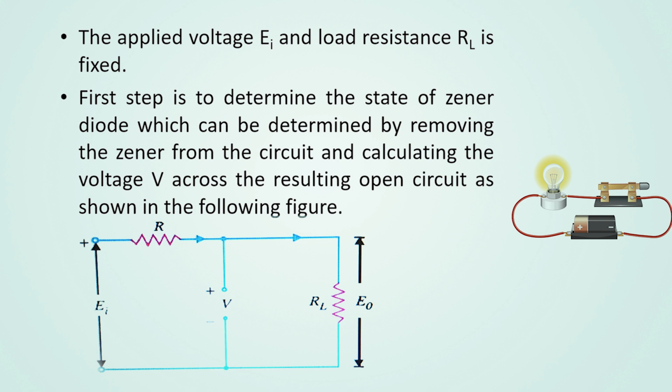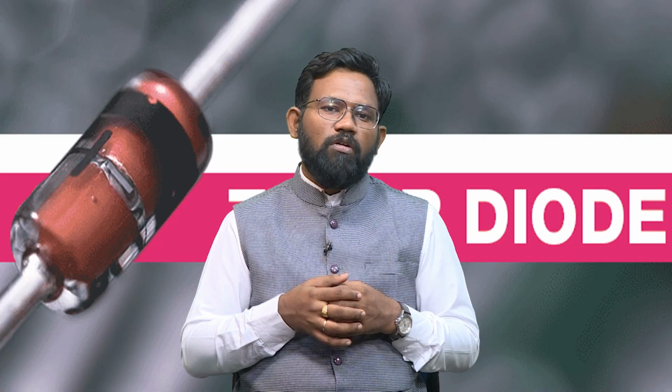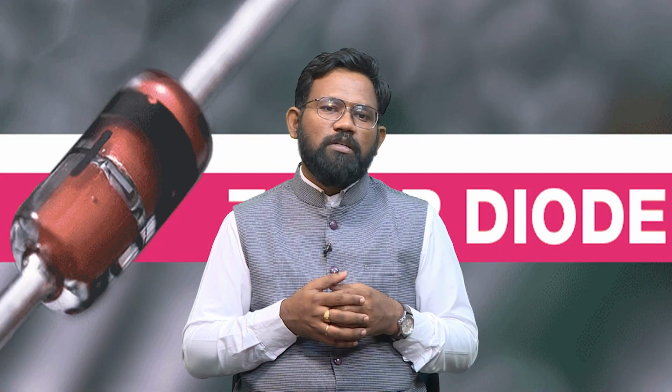So, the first step is to determine the state of the Zener diode, which can be determined by removing the Zener from the circuit and calculating the voltage V across the resulting open circuit as shown in the figure. Here, the Zener diode is removed and the voltage is calculated across it, keeping the rest of the components, that is the series resistance R and the load having the resistance RL. The voltage is E naught and the fixed supply voltage is EI.